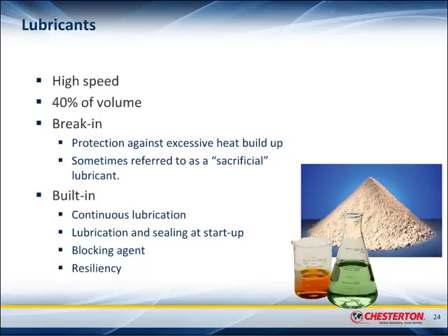There are two main types of lubricants. First type is break-in lubricants. That's the packing that you saw in the beginning of the last video, where a braided packing is pulled through a bed of lubricant, and this lubricant stays on the outside of the packing. So protection against excessive heat buildup, specifically in the beginning.